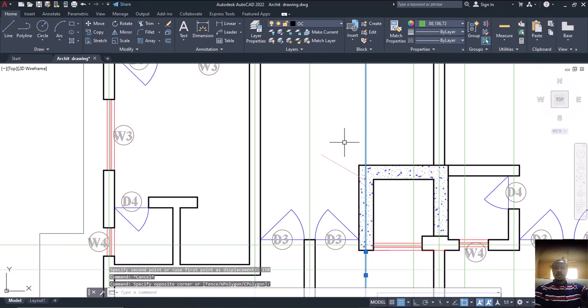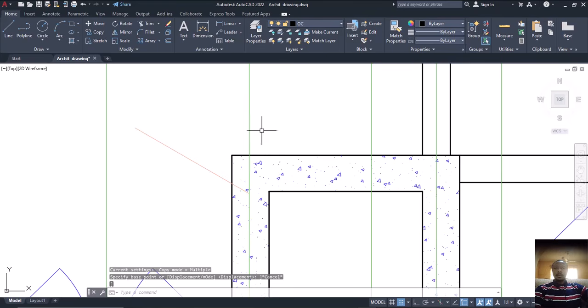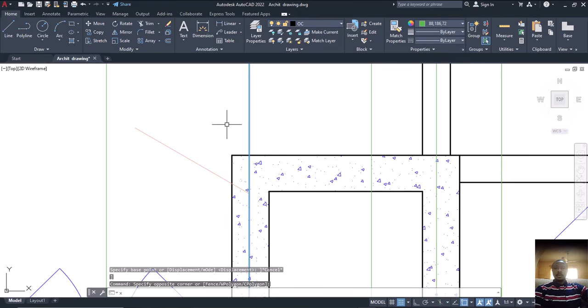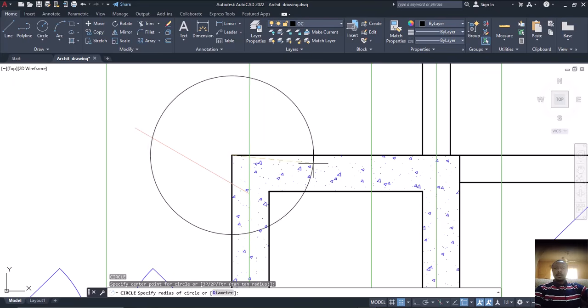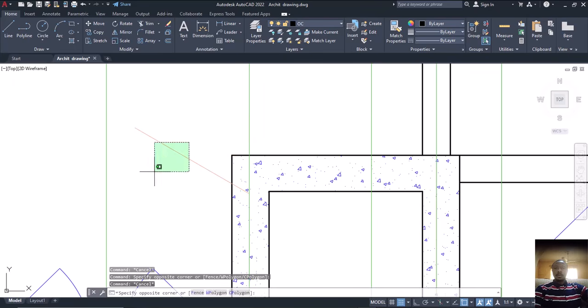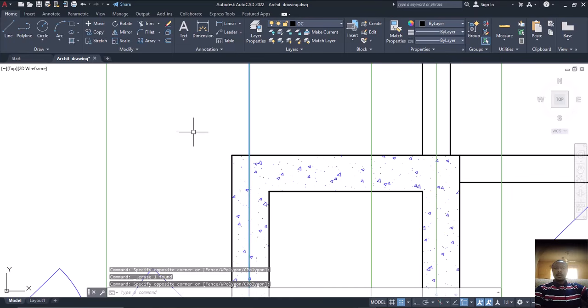So I cannot copy from here now, CP, enter. Then from here, we already have one here. But for this particular shear wall, let it have its own. Okay, CP or CO. Sorry, click on this, remove this, click on this, CP or CO, enter. From this edge now, I'll come here and fix it here. So this is center. Is that okay?